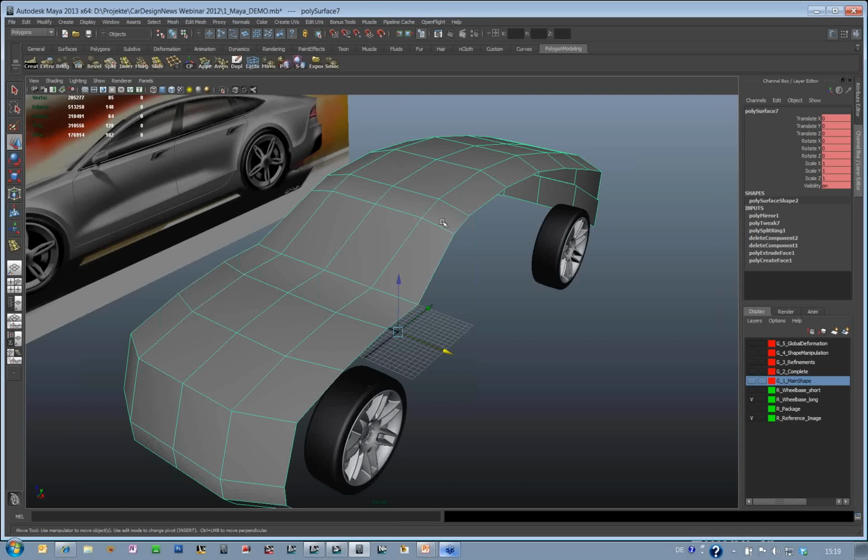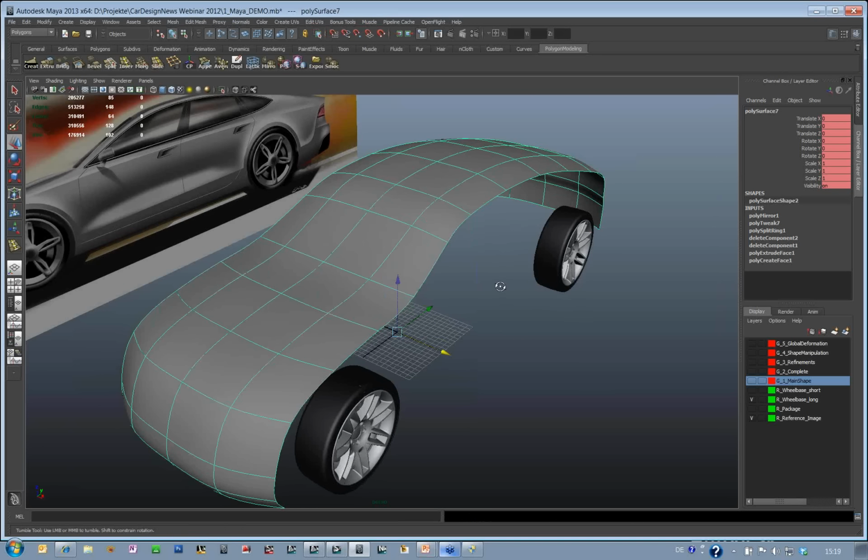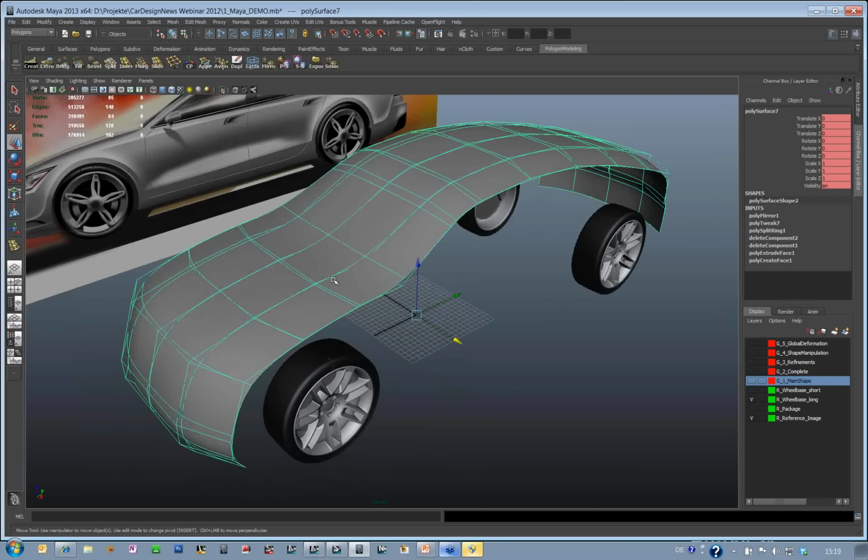And if I need to turn this really rough, not so smoothly defined shape into a nice smooth polygon surface, I use the keys 1, 2, and 3. Key 1 controls the rough polygon level, key 3 smooths this polygon level, creating some kind of interpolation between the polygons, and key 2 turns both views on in one step.